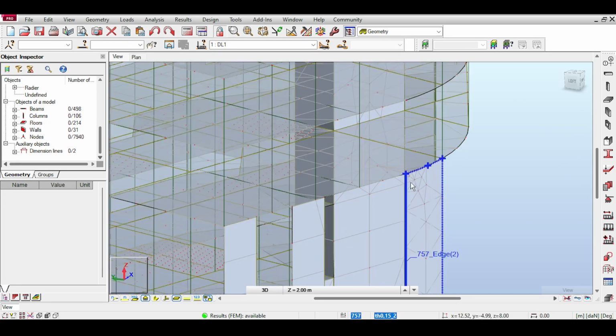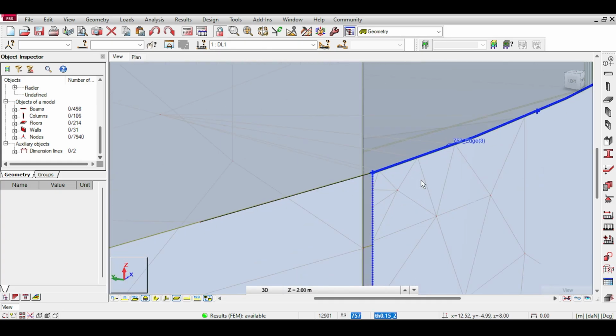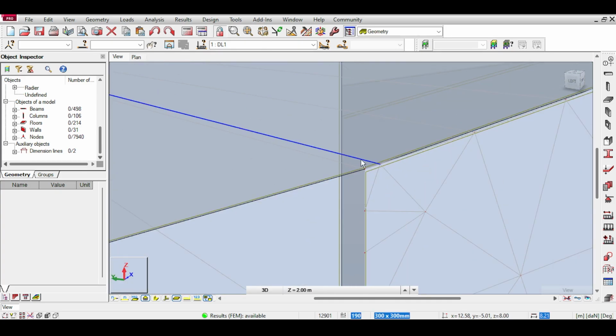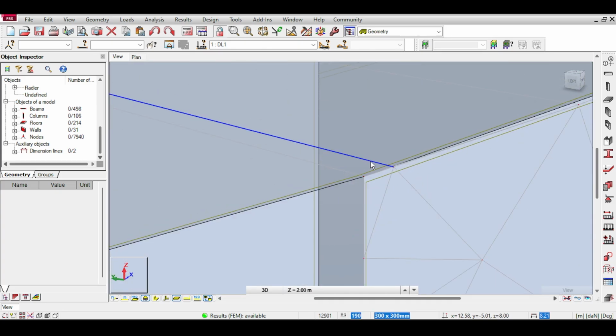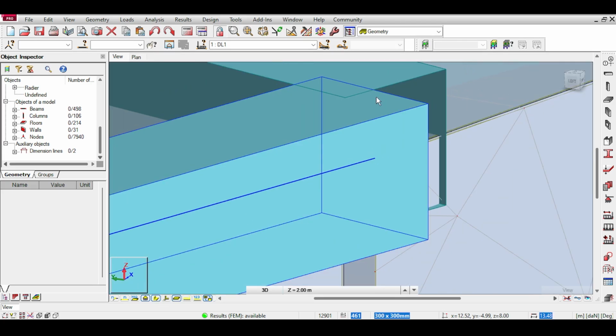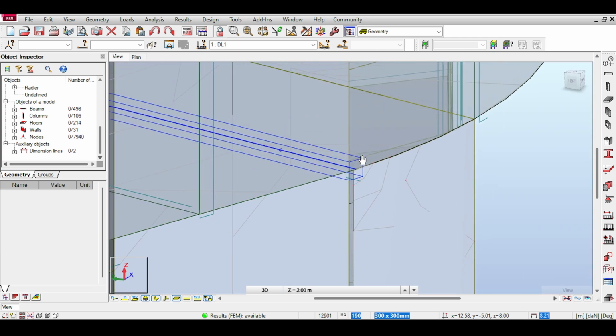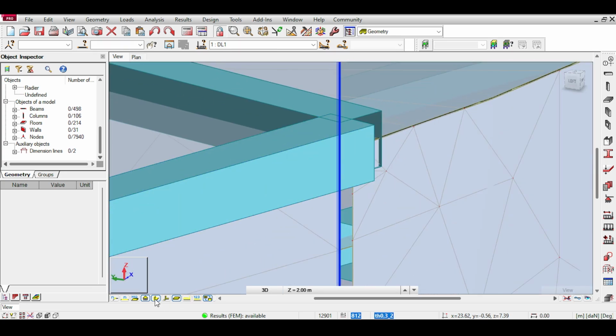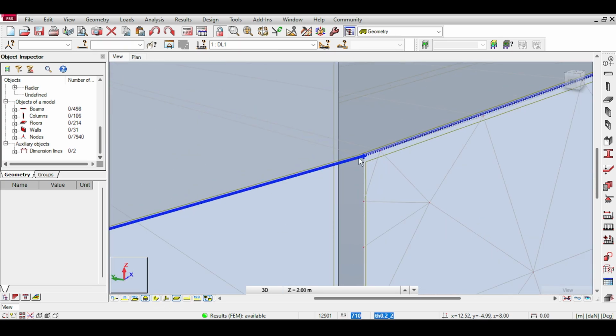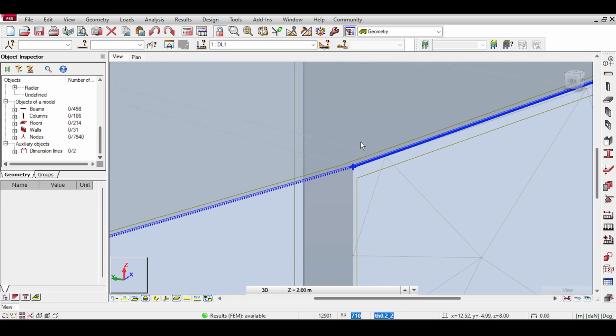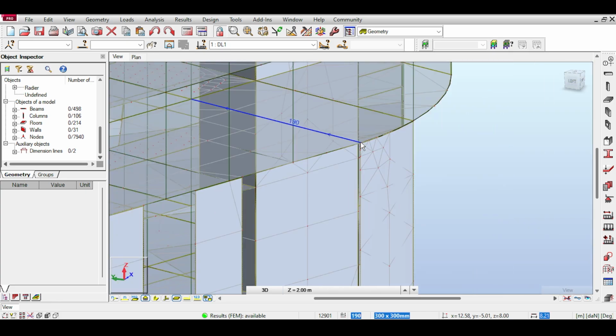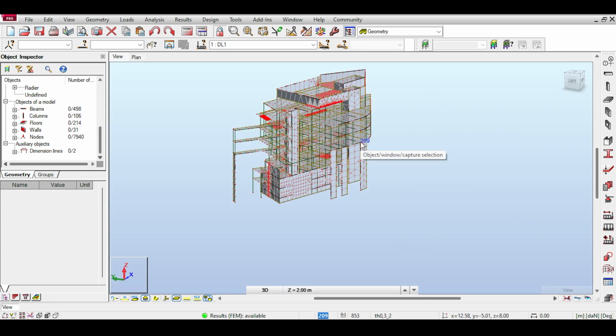that. I mean, look, this is another contamination here. You can easily check. I'm pretty sure it's the same. See, same shenanigans. You have a column that is misaligned with the wall, that is misaligned with the beam. Like, look, if you open the sections, beam, sorry. You can see two beams which from the outside look perfect, but if you just remove the section, you can see that those two beams actually misalign, and Robot struggles in meshing that thing. Those are my comments on the mesh.